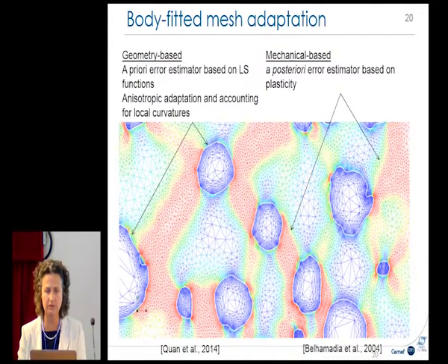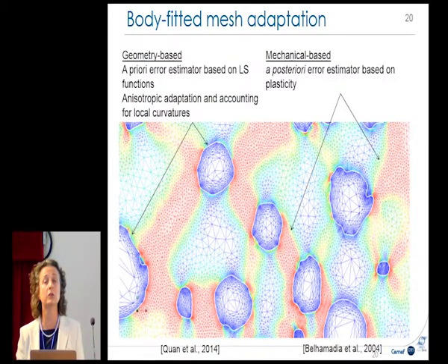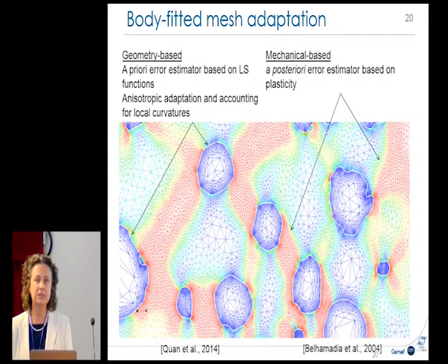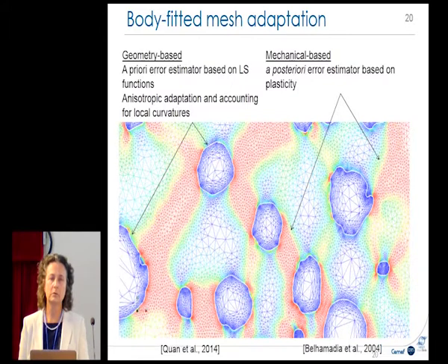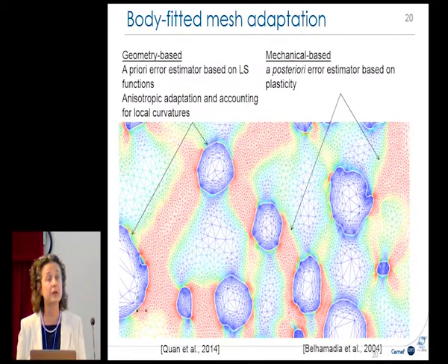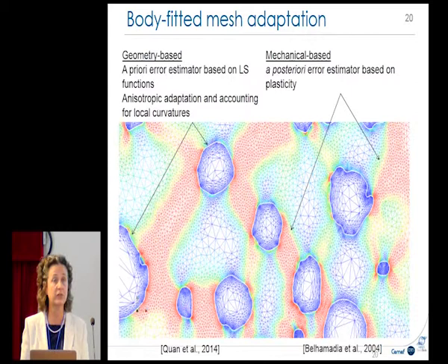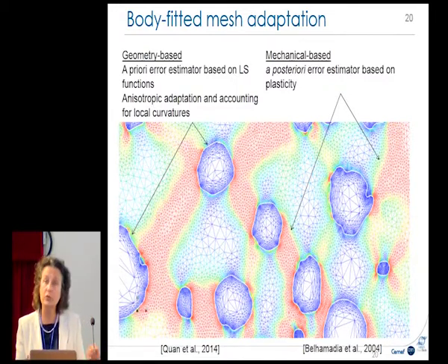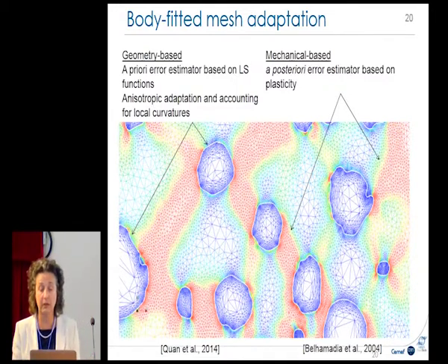So the second part is the application of this microscale studies on the knowledge of the evolution of damage. The damage can be coming from the initial casting. For example, we can have some void in the initial part, and progressively, due to forming, we can have the evolution of this void until rupture. But we can also have the closure of this void. This could also be interesting to be able to simulate.